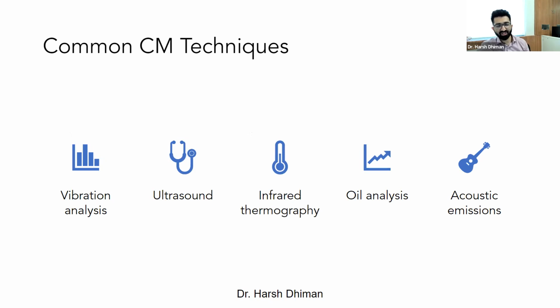You have vibration analysis, a very common, popular technique. People in industry 4.0, especially with all the rotating machines, vibration analysis is one of the methods where, I would say, 90% of the time they are reliant on the results obtained from vibration analysis. Then you have ultrasound techniques, infrared thermography, oil analysis, and acoustic emissions as well.